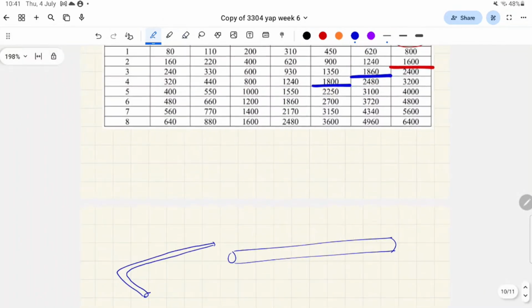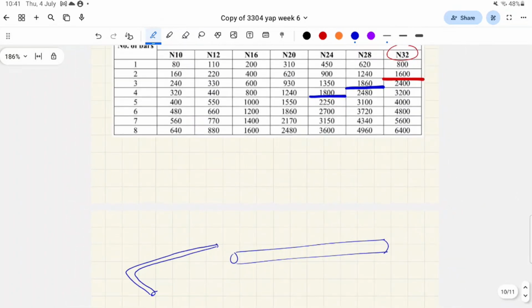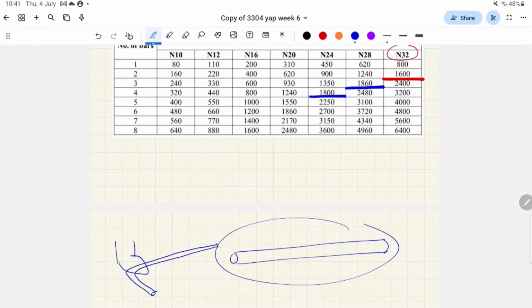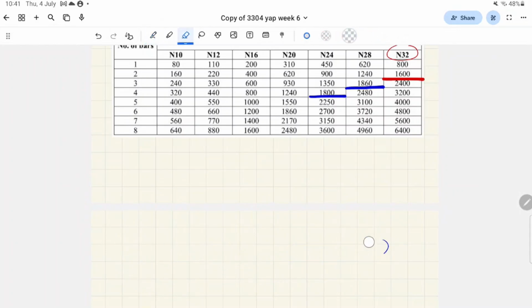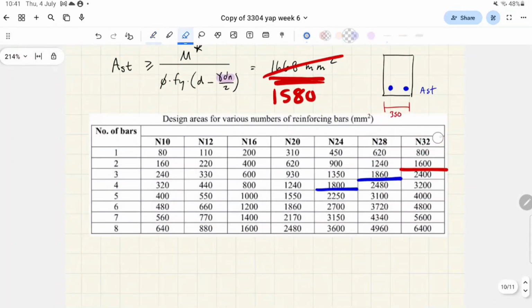And N20s are relatively easy to bend, right? Even N24s are okay. Once you start reaching N28, N32, good luck bending this. What they have to do is get their steel cap boot and use bending moment to bend it. But it's basically impossible with this diameter, right? And the material properties. So they avoid N32s where possible, essentially.